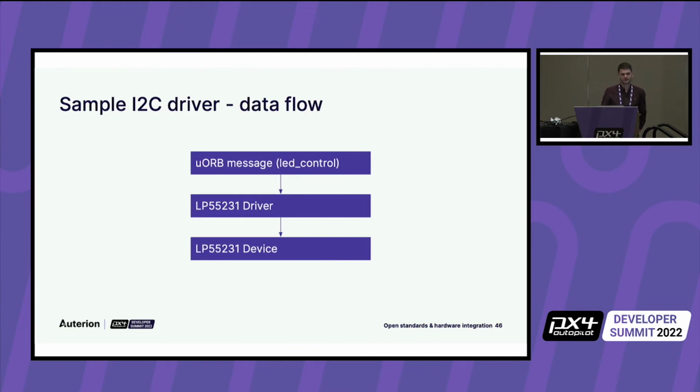So drivers either just consume data on a certain topic and use that to drive some hardware, or if it's a sensor driver, then you read out some metric from your sensor and you publish it over uORB to be consumed by other modules. So really, it's just writing a module that consumes the data and then does some physical action. Or you measure some physical action and you send out the data over uORB. That's really all it is.